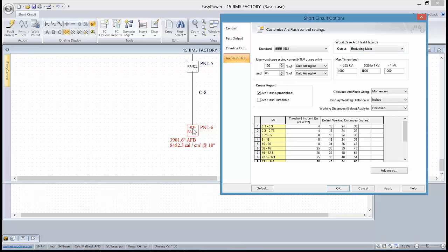In this case, it's a fuse, so we're excluding that from calculations. Several places in previous discussions we've talked about why this is the case, but essentially it goes down to whether or not that breaker or panel or protected device is isolated from the rest of the system. You're welcome to send me an email if you have a question about it.